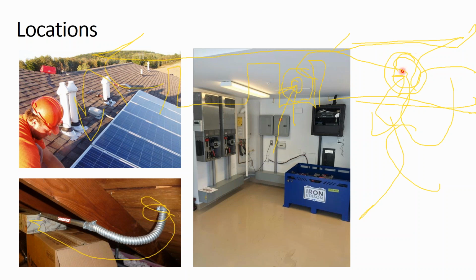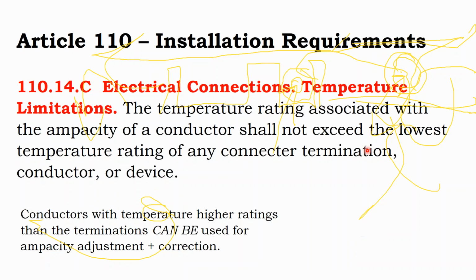If you leave that gap there, the moisture from the outside can get into the inside and cause it to rain inside your conduit and cause a leak down the line. And if that water stays inside the box and you're in a freezing area, over time the winter hits, and now you have ice inside your box, and that ice starts trying to break your box apart. Small problems can eventually result in big problems.